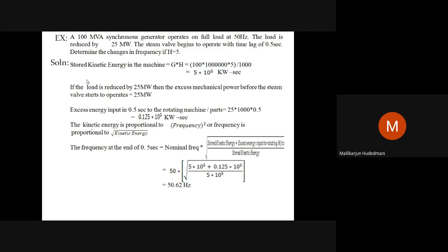That is called the lag timing of the steam valves to close. How long? They take 0.5 seconds. Once you give a command to close the valve, reduce the fuel to the turbine. That's the command when the load is decreased. Otherwise, frequency would shoot up. In that perspective, valves have to be closed down. Then to command it and act on it, really, the lag is 0.5 seconds.